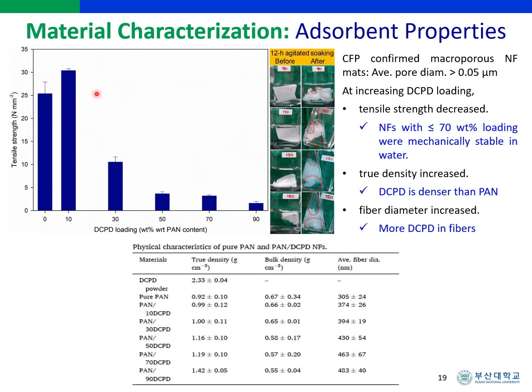NF. At 10 weight% loading, most of the DCPD particles were uniformly distributed within the PAN nanofibers, resulting in a good PAN-DCPD interaction, thereby reinforcing the fibers. However, as the DCPD loading increased, the tensile strength of PAN-DCPD nanofibers declined significantly, owing to the increasing degree of DCPD agglomeration, starting at more than or equal to 28% loading.